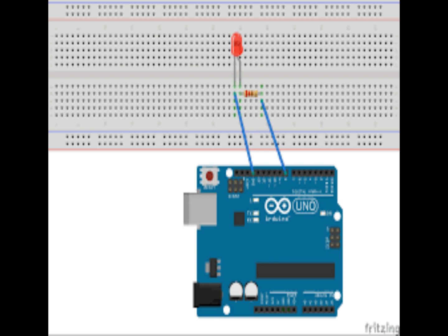Plug the resistor and then the LED directly into the breadboard by just pushing its metal pins inside until fixed. Make sure they are positioned exactly as in the image, one directly above the other. When done, take 2 jumper wires of different colors and connect them to the ground or GND and pin number 13 of the Arduino Uno. Then, connect the GND jumper wire to the straight pin of the LED, not the one with the pre-existing bend, or it will not work.